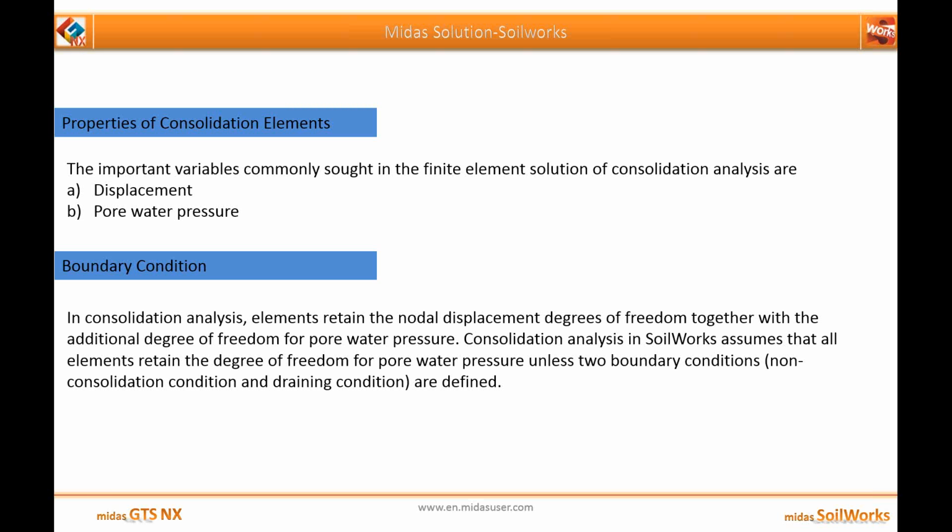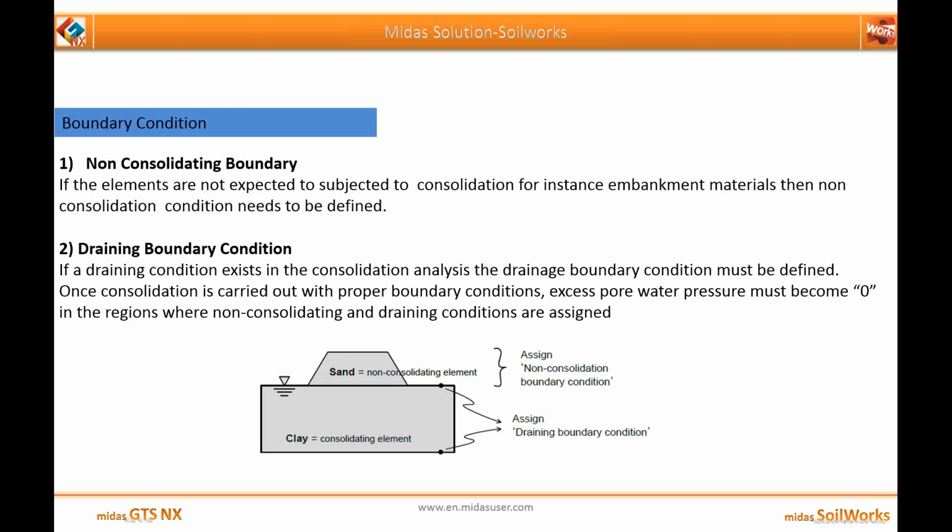Consolidation analysis in SoilWorks assumes that all elements retain the degree of freedom for pore water pressure unless two boundary conditions, namely non-consolidation condition and draining condition, are defined. So you must make sure that you use these two boundary conditions to properly define your exact material or drain property. Now, what exactly are these boundary conditions?